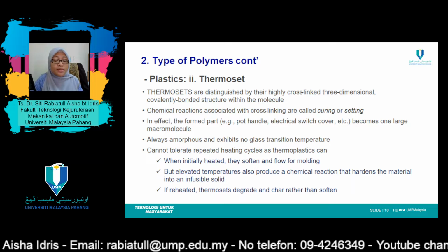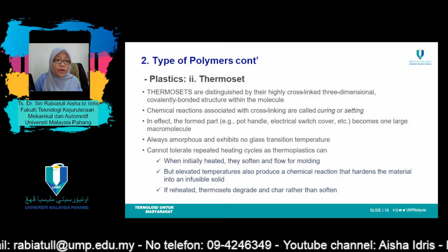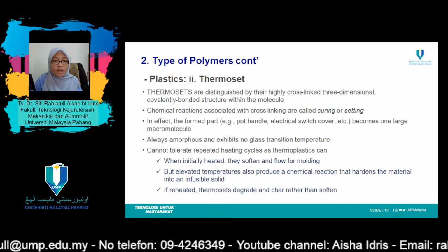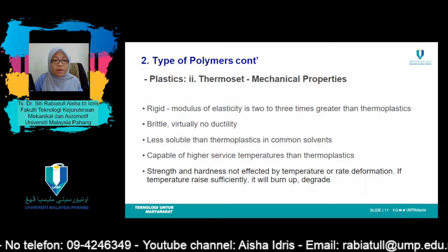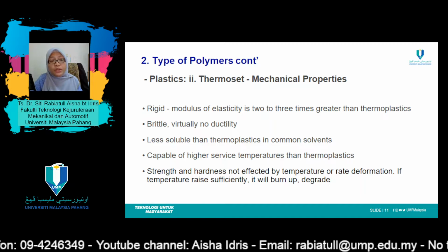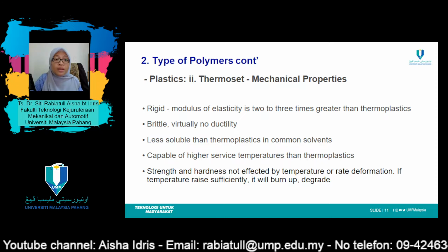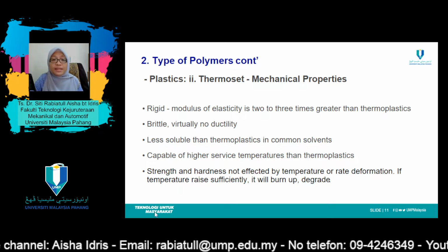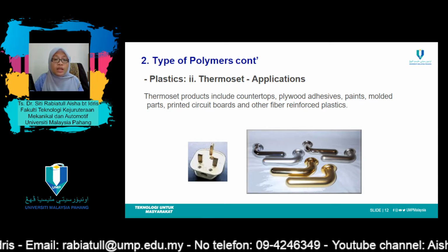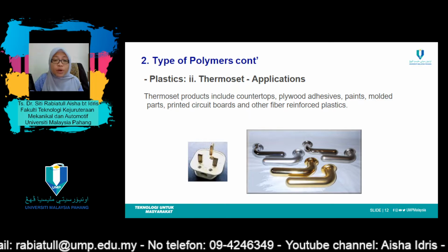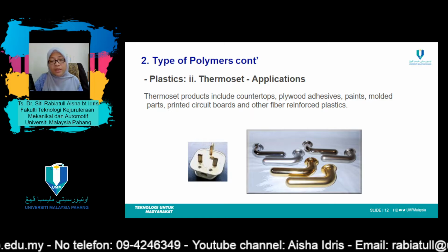Cross-linking is normally extensive in that 10 to 50% of the chain repeat units are cross-linked. Only heating to excessive temperatures will cause severance of these cross-link bonds and polymer degradation. Thermosetting polymers are generally harder and stronger than thermoplastics and have better dimensional stability. Most of the cross-linked and network polymers, which include vulcanized rubbers, epoxies, phenolics, and some polyester resins, are all thermosetting.